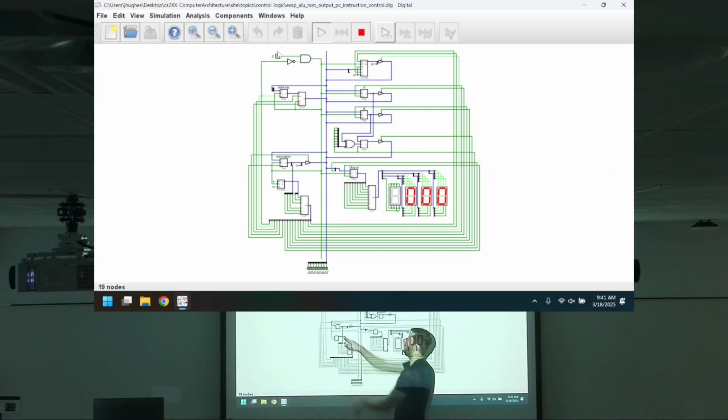Because no matter what, whatever is in the instruction register, it's going to be a no-op, because whenever we turn it on, it's no-op. But even if this was physically designed and I turn it on, and a random instruction is in here, which it would be in practice, the first two steps that the microcode counter will have will always do fetch. So we're going to fetch.